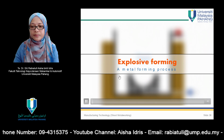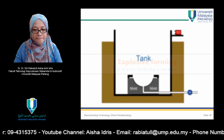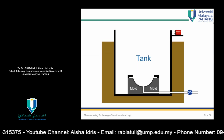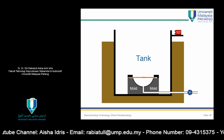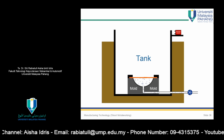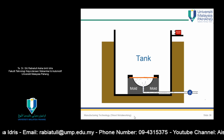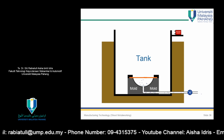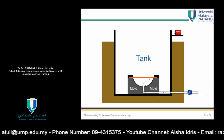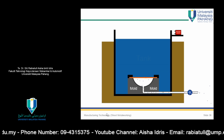Explosive forming is a metalworking process that uses energy from an explosive to form a metal into the shape of a mold. The sheet is placed on top of the mold and the air beneath the sheet is evacuated. This is done to prevent the air from stopping the metal sheet from being pressed into the mold once the explosive is triggered. Next, the tank is filled with water to maximize the effect of the shock and pressure wave.